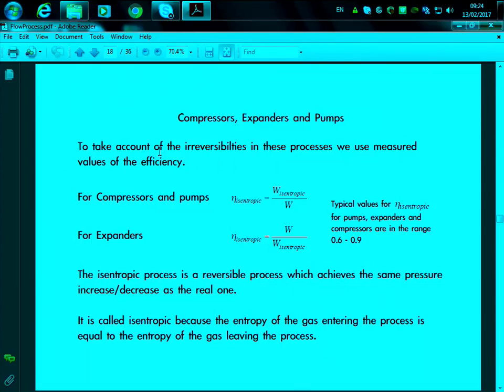Okay? But we also recognize that a compressor will have certain losses. So we initially assume that a compressor behaves isentropically, so it's an isentropic process. But then later, this will help you calculate the work at isentropic conditions, but in order to get the real work that you have in the system, you need the isentropic efficiency.